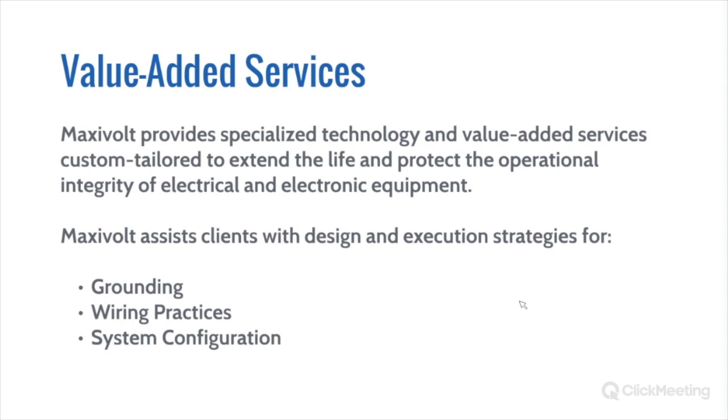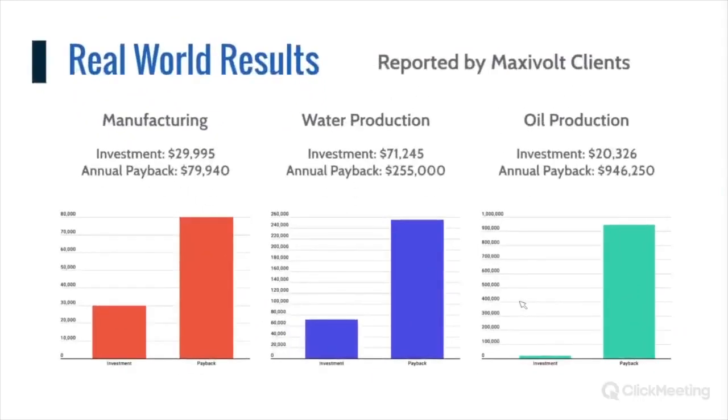Yeah, and so Alan, to your point, to actually do power quality correctly, it's not about sticking Band-Aids or some little widget out to take care of all my problems. There is no magic solution or no magic answer that takes care of everything. It's a matter of priorities and understanding what needs to get done first. But you have to look at the whole system. We can't just say, okay, I have a 480-volt system, therefore take this approach and it works all the time. The type of system, whether it's a wye system, a delta power system, a corner grounded delta, all these other variabilities start throwing a lot of complexities and a lot of other concerns into there.